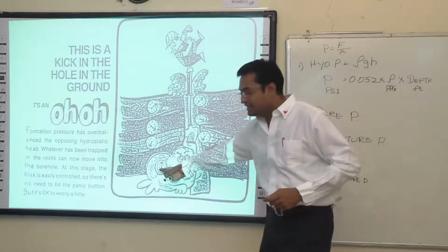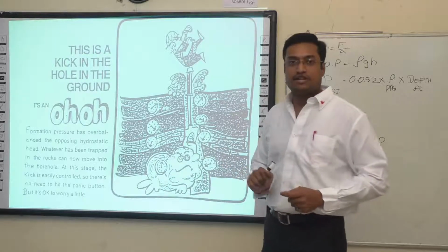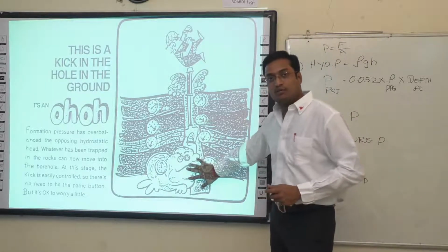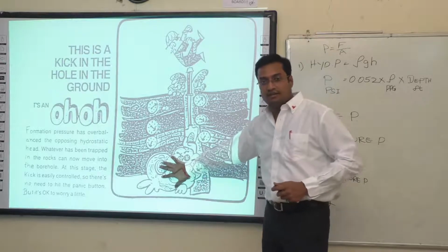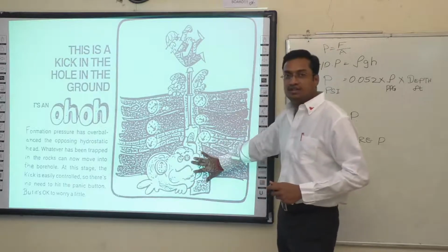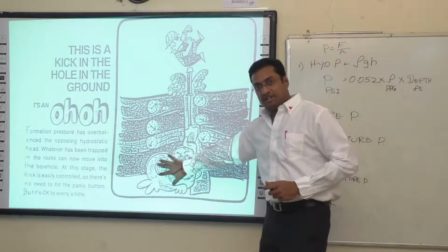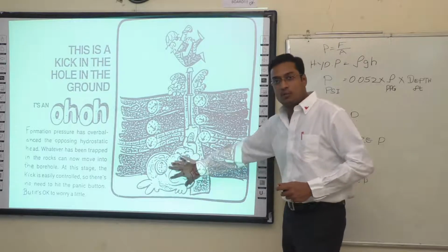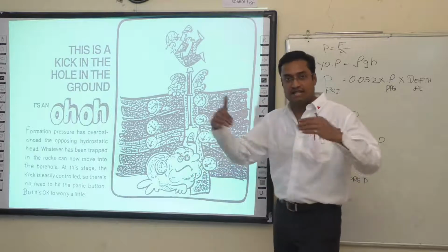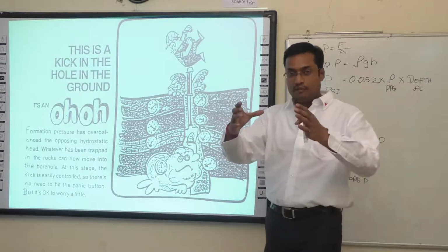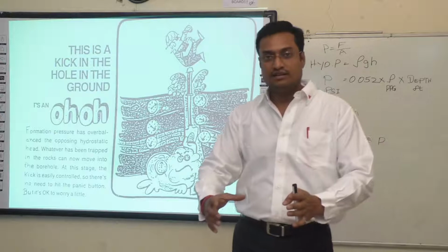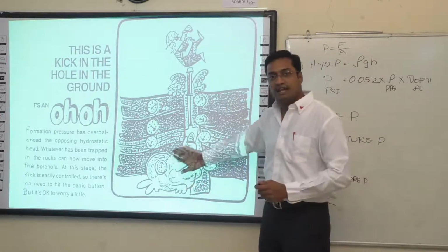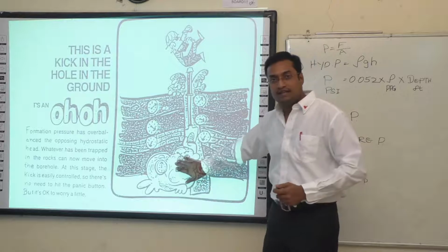becomes less than the formation pressure or the pore pressure, we go into an underbalanced condition where we wake up the giant and it's going to act on us. So when the pore pressure tries to get inside the wellbore, which means the hole which we have drilled, if the pore pressure starts entering into the wellbore, that is a kick.